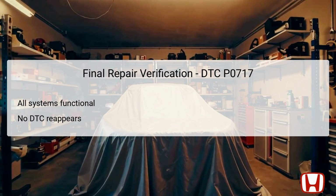During this phase, professionals should run the vehicle to replicate the conditions that previously triggered the DTC. If no codes reappear and the CVT operates smoothly, it confirms that the underlying issue has been effectively resolved. This verification step is vital to assure both technician confidence and customer satisfaction.